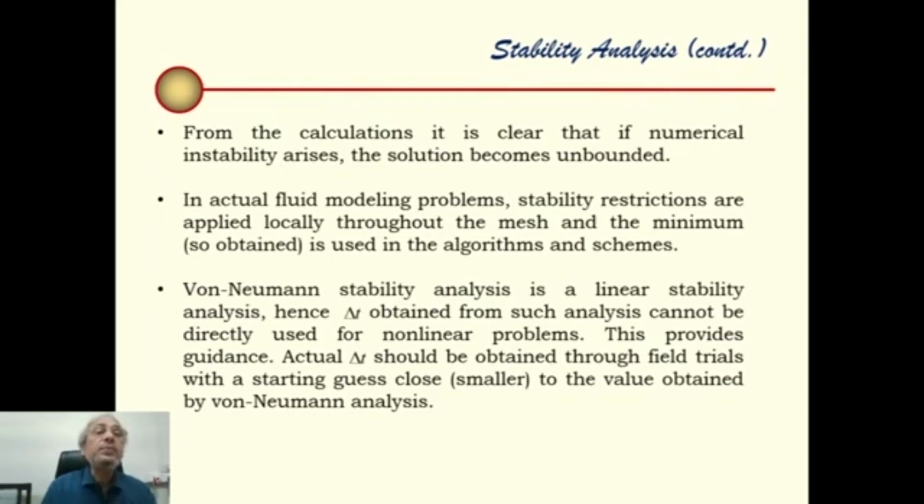One may argue that if we go for implicit formulation, we don't need that. That is true. But when I mentioned it earlier, when we want to capture exact transient, especially for turbulent flow problems, when we calculate for direct numerical simulation or large eddy simulation kind of scenario, every time step, intermediate time step is meaningful, then we cannot avoid this explicit advancement rule.